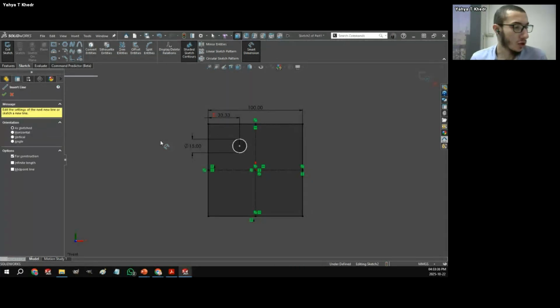So I'm not sure if any of you have heard of the tool called the segment tool inside of SOLIDWORKS. If I'm not mistaken, it's been around since 2015 or something. It's a pretty old feature in SOLIDWORKS, but not many people use it. So the segment tool pretty much creates equal sized segments of whichever sketch entity that you give it. It can be a line, it can be an arc, it can be a circle, a spline, whatever it is, it's going to divide it into equal segments, okay?